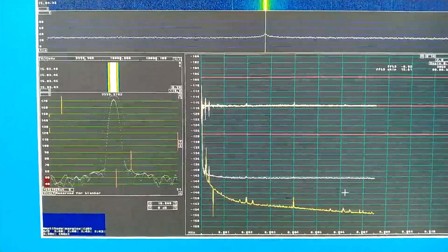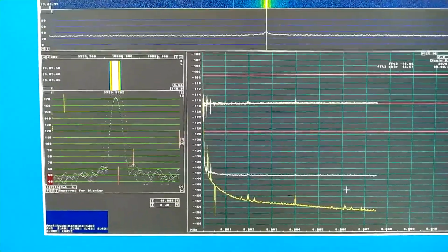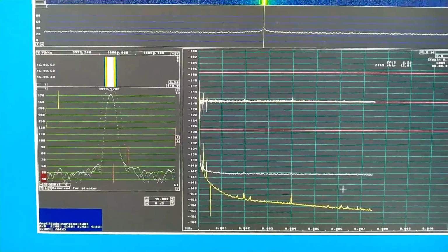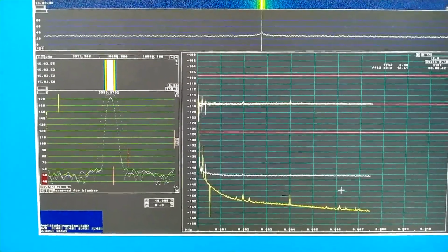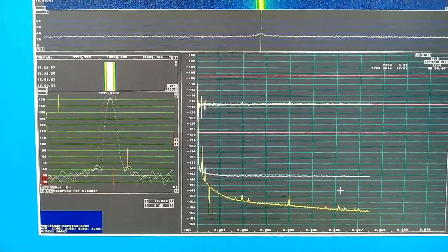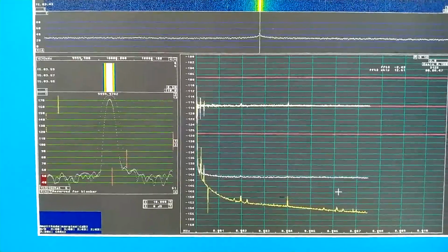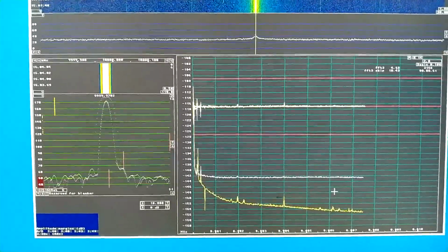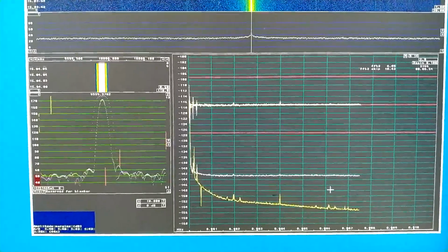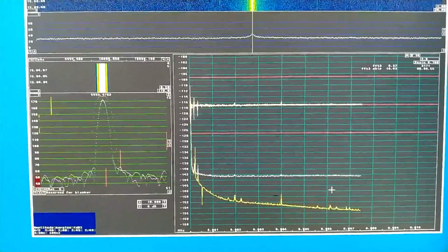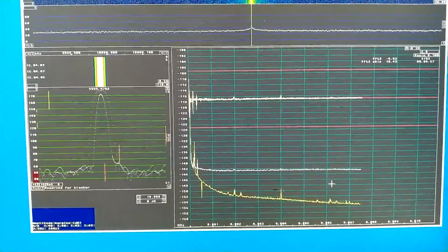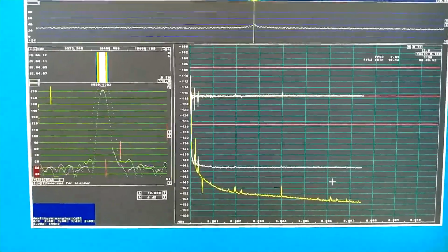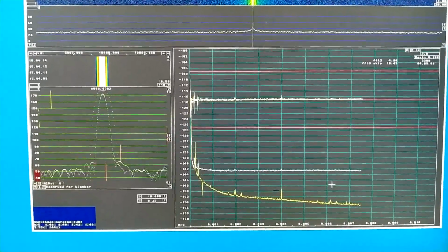And preferably not the smallest size. All places where there is an RF voltage should have such capacitors in low noise systems. Only big decoupling capacitors can be some other kind of ceramic material. Even better is to use plastic film capacitors.